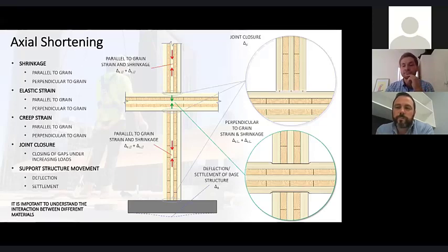And from my perspective as the builder, we would never have let you go down the castellation, because it's an absolute pain, a huge amount of money, and really difficult to install. You're dropping another level of tolerance in there, and especially if you're getting some moisture in the timber and those castellations start to swell, you've got a 12-metre long by 3-metre high piece of CLT on the hook, trying to thread all these needles. It can work, but I'm not a huge fan of it. Yeah, totally agree.